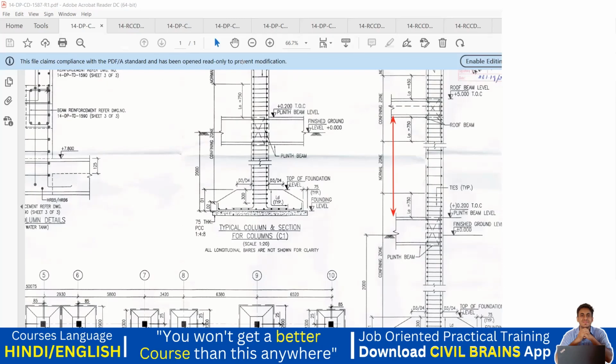The code says, if you refer to the earthquake detailing code, IS 13920, which is for ductile detailing, that from here to here, this much portion, and from the slab to this much portion, you're going to do the confining reinforcement. That means here you're going to keep the lateral ties, that is your stirrups. In a column they are called lateral ties, at a much lesser spacing. That is why you can see the lateral ties here placed at very close spacing.